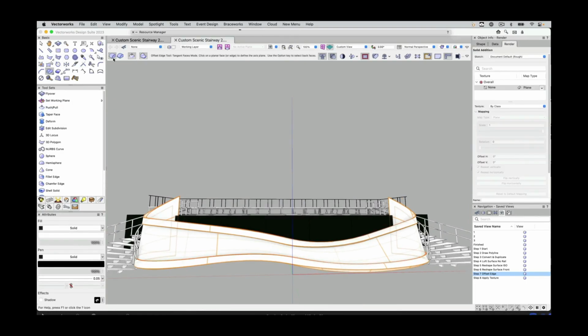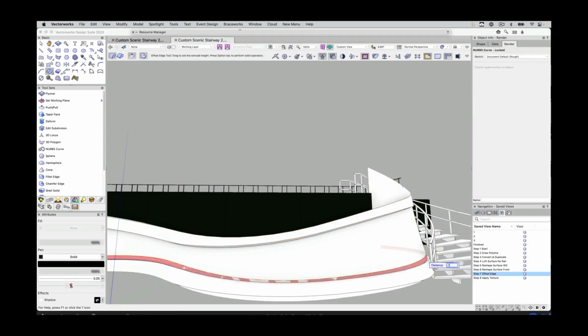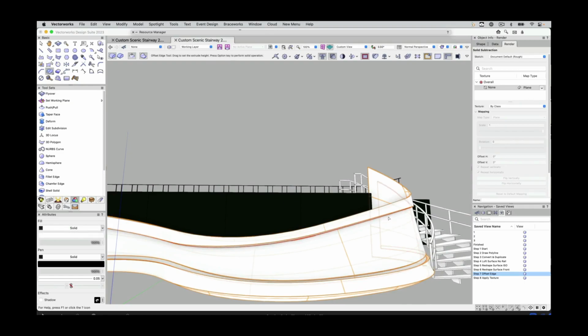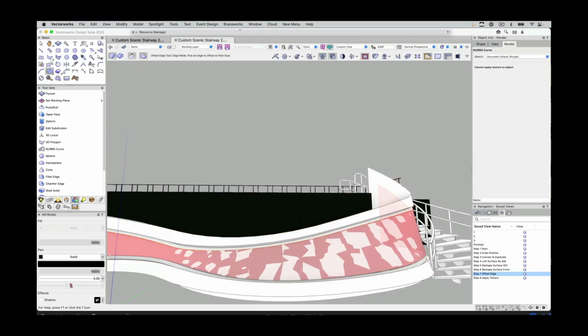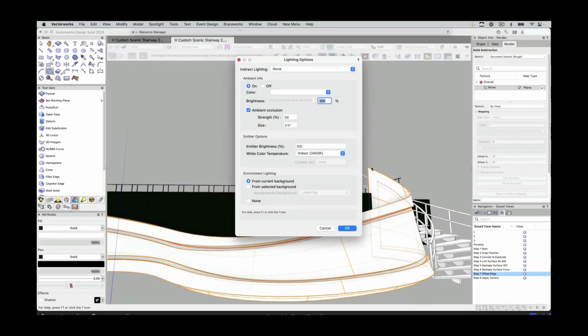Now that was the second mode of the tool. The first mode of the tool is just to select a single edge. Let's select this inner edge, select that yellow arrow, we'll go up 4 inches, and then we'll recess it minus 1 inch. Same thing in the direction we want to go, 4 inches, and then it goes right into the push-pull mode, minus 1. Now I want to apply some texturing to these two channels.